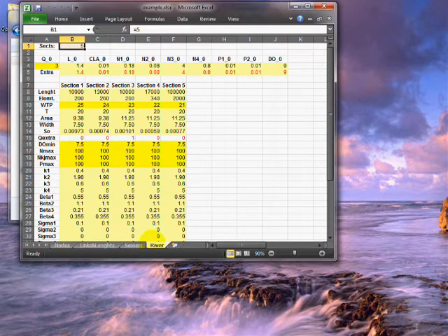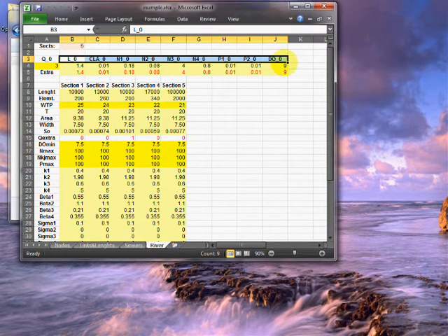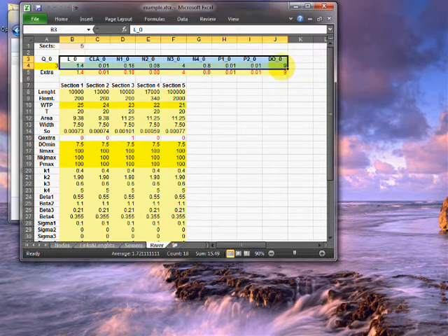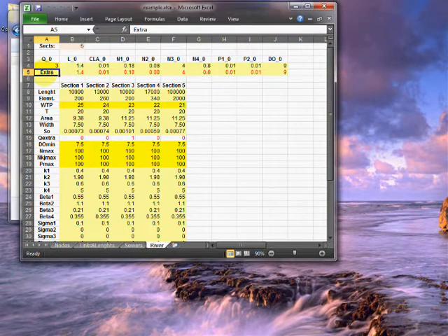The last sheet has all the information on the river, which in this example has 5 reaches. The rows in the top contain information about the main river, such as the river flow and the initial values of its water quality indicators. These rows also contain the water quality indicators for the river's tributaries. The flows of the tributaries are defined in another row. They are considered as extra flow and are added in the reach where the tributary is located.